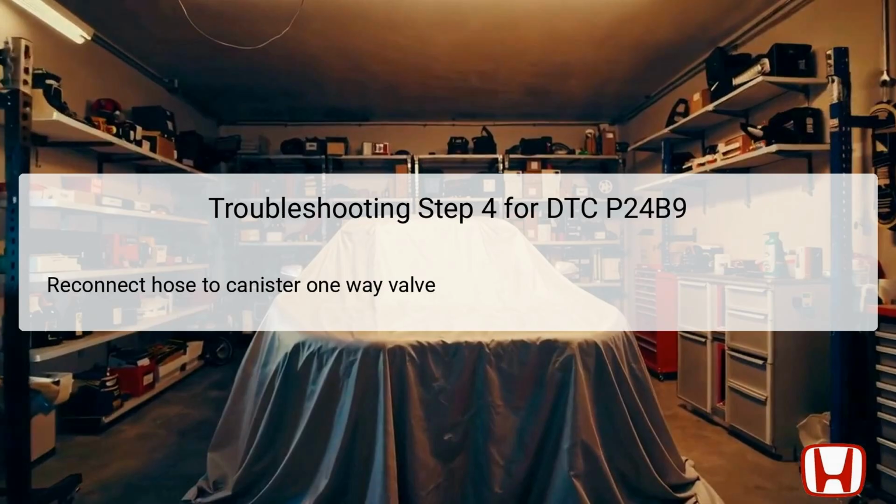By applying pressure through the vacuum pump to this component, the technician can assess its operational integrity. Any issues with the canister one-way valve can lead to misreads of pressure levels, potentially contributing to the triggering of DTC P24B9. It is essential to monitor the pressure levels after connecting the hose and applying pressure to determine if the readings are consistent with normal specifications.